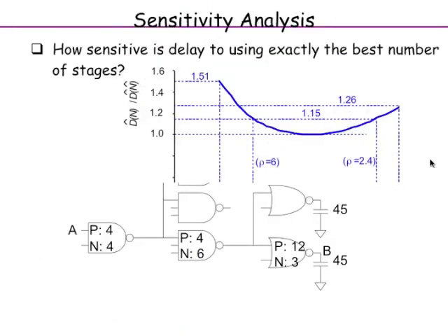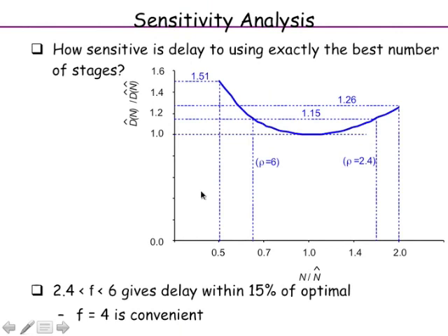And so that is why, if you plot this, the delay as a function of the f opt or the number of stages, which is kind of equivalent, because when you have one, you have the other. There is a kind of shallow delay out here. That means f is 3.5, 3.8, 4, etc. The delay is small. I mean, the delay is kind of close to the minimum.